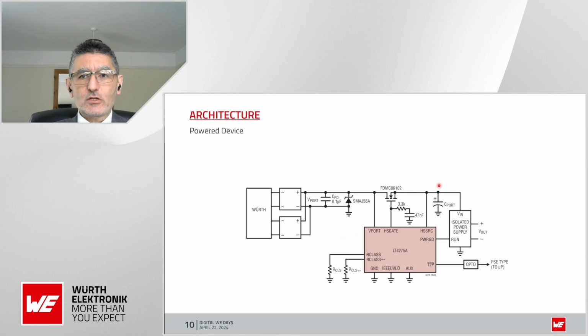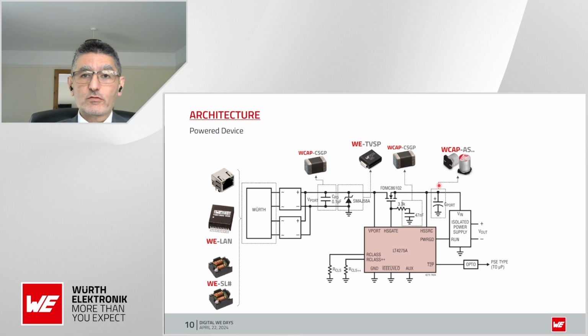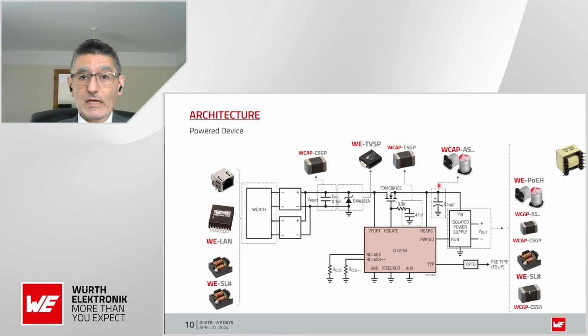And I'll finish off this section on concept and architecture by showing you some of the solutions that we, as Würth Elektronik, are happy and capable of providing you on a system like this. On the input side, we have the discrete RJ45s, as well as the discrete LAN transformers or the integrated ones. We also have a wide range of EMC components that we can use on the front end, overvoltage protection in the form of transient voltage suppressors, as well as, of course, a wide range of filtering components for EMC, as well as for the power side of things, be it transformers, filter inductors or capacitors.